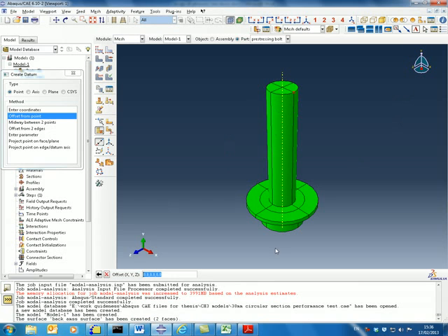I'm working in the Y direction on the negative side, and I'll select 10 to create the datum point. This is the first point. The second point goes from down and up in Y, and it has the same length as the back mass, which is 36 millimeter. So it comes up to here.